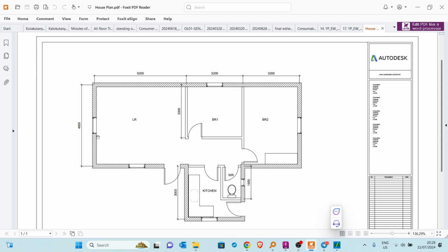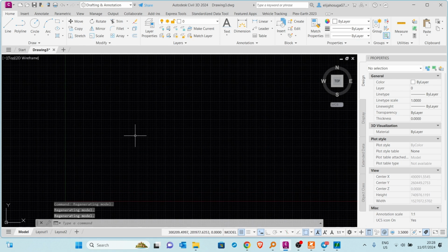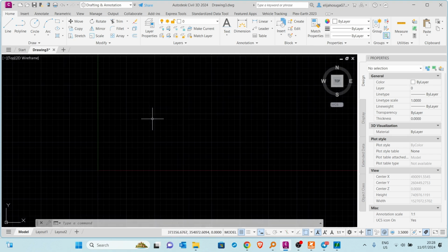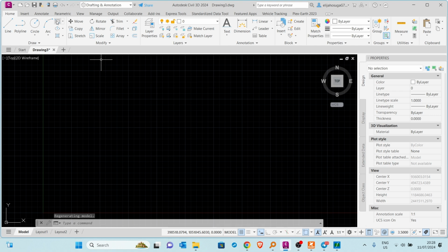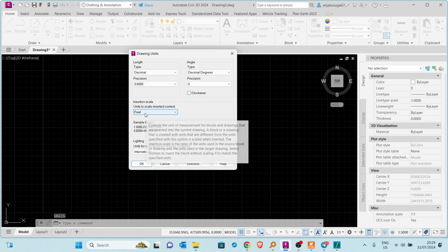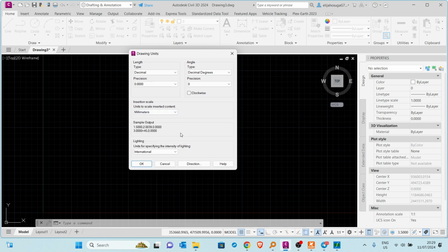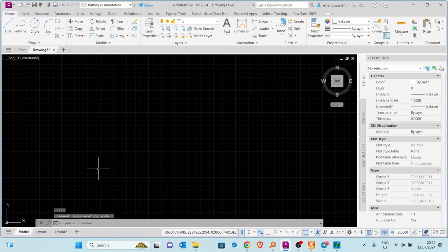Okay. So let's first of all draw that rectangle. These things are very simple. We'll do a very simple plan, which can now help you to do even more complex plans. We always start with simple stuff. So I can draw a rectangle here. Before we do that, we have to start from the units. Always set your units first. Millimeters. My millimeters are my units. Okay. Good. Once you set up your units, you can now start laying out your geometry.